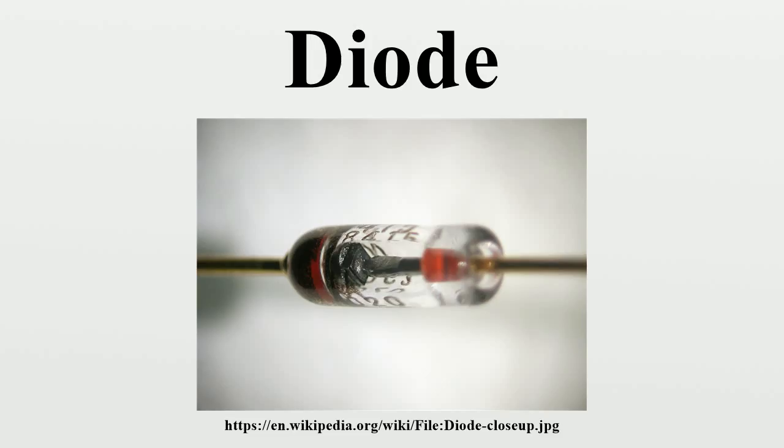So a current of electrons flows through the tube from cathode to plate. However, when the polarity is reversed and the plate has a negative voltage, no current flows because the cathode electrons are not attracted to it. The unheated plate does not emit any electrons itself, so electrons can only flow through the tube in one direction, from cathode to plate.